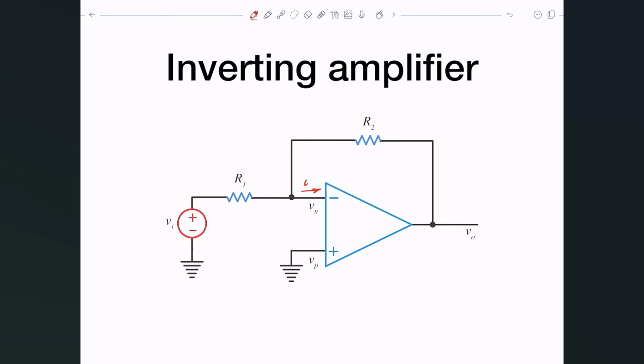The assumption is the negative current, or the current going into the inverting input, is 0. And also the current going into the positive input is 0, and of course, because the open loop gain, what we called A, creates what we call a virtual short in here, and in virtual short, I know that Vp is 0 because it's connected to ground. That means also Vn is 0. So let me just write these here. So what we have is In is equal to Ip is equal to 0, and we have Vp happen to be 0. That means Vn is also 0.